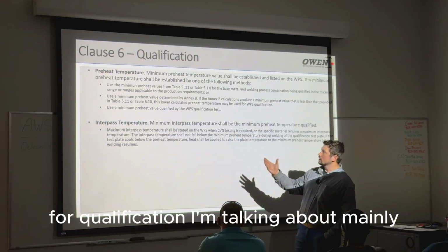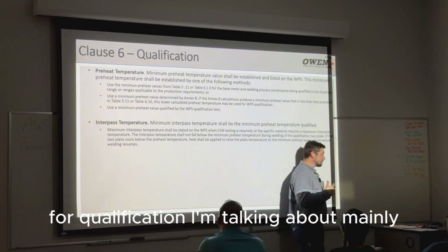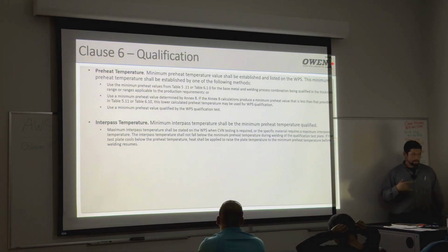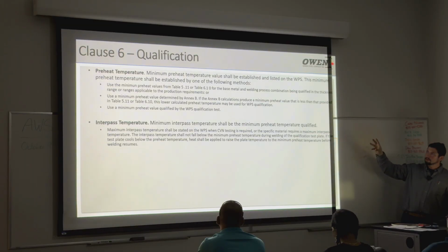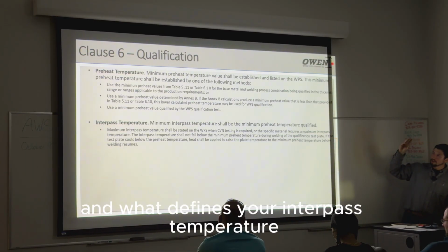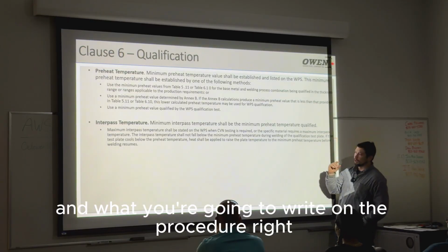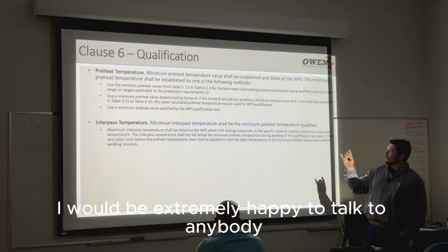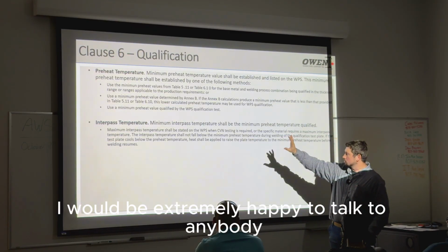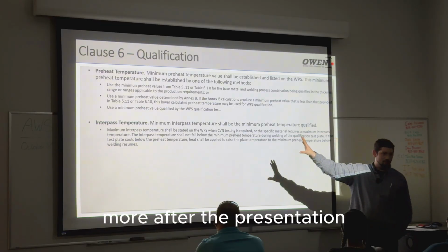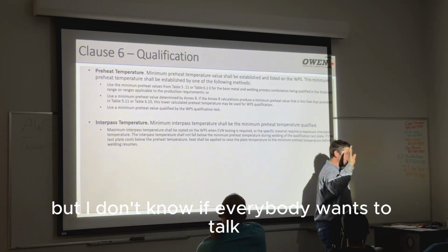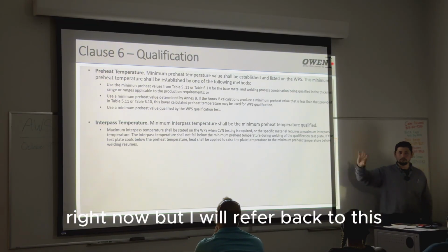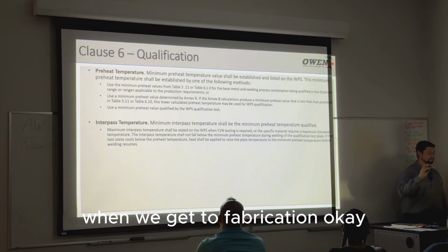For qualification, I'm talking about, mainly this is tying back to procedure qualification when I'm writing a WPS. They talk about how you should qualify your preheat temperature and what defines your interpass temperature and what you're going to write on a procedure, right? I would be extremely happy to talk to anybody who wants to talk about this more after the presentation, but I don't know if everybody wants to talk about the nitty-gritty of preheat and interpass temperature qualification right now. But I will refer back to this when we get to fabrication, okay?